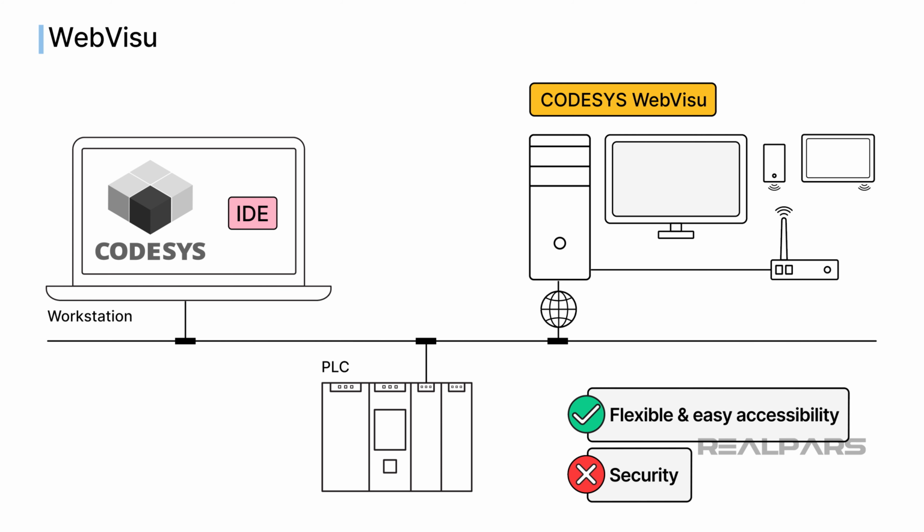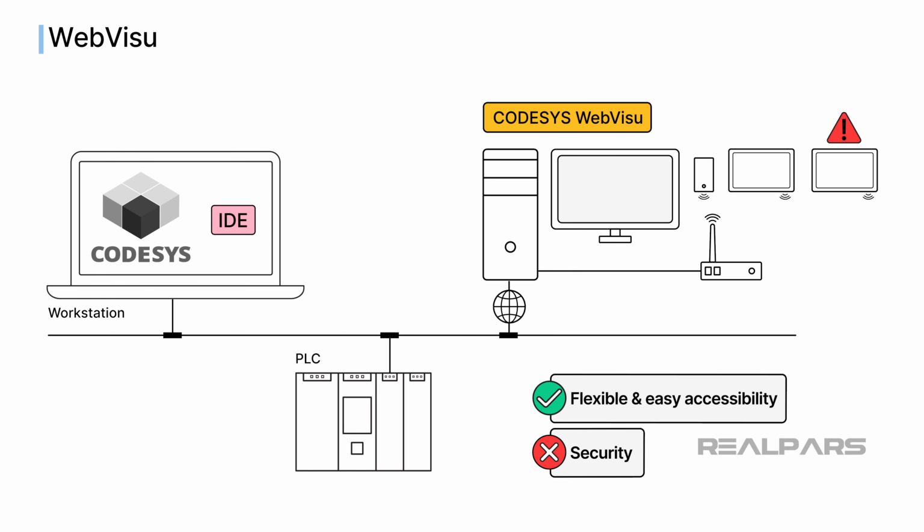The disadvantages of using a WebVisu deployment all revolve around security. Since any device on the same network as the runtime can access the visualization, you must take extra care to implement proper user management in the visualization and security on the network.